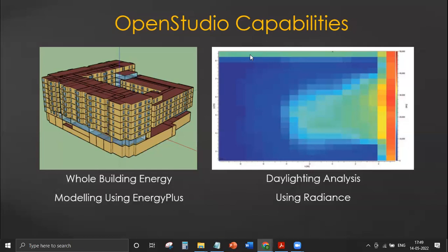So measures are tools or macros. You can correlate it with the macros of your Excel developed by various people, which you can just drag and drop. If you want to model a chilled water system, or you want to model a VRV system, you only have to drag and drop that measure, and the code itself will change your model and will model the central plant or VRV.